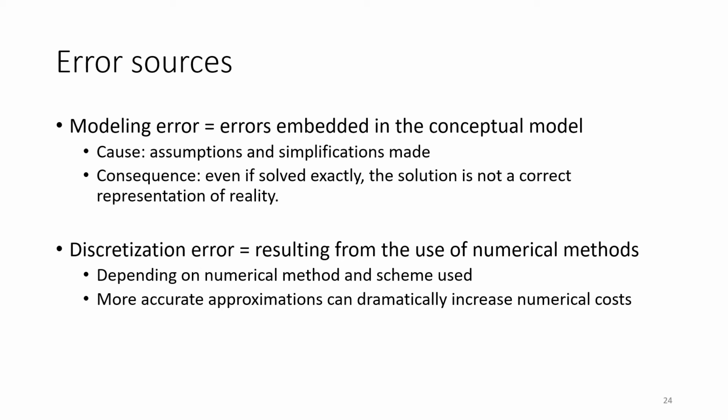As an example, when you're modeling groundwater flow, you will assume the density constant. This common approximation works really fine. Still, if there are pressure variations or temperature variations, the density is varying along your aquifer. So there is a difference between our model and reality. This modeling error is probably very small, and we really don't care about it because we have other error sources which are way more crucial than that. But still, there is this error.